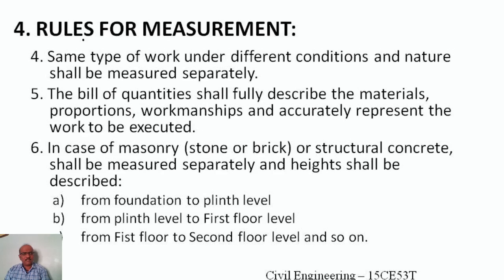The next one is if the same work is to be carried out in a different condition or at a different time, those have to be measured separately. For example, if the same reinforced concrete is laid in foundation, columns from foundation to plinth, or column casting from plinth to first floor, second floor, the beams in plinth beams, roof beams, first floor beams, second floor beams, like this. The same item carried out in a different condition or at a different time has to be measured separately.